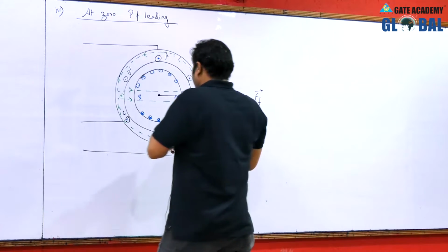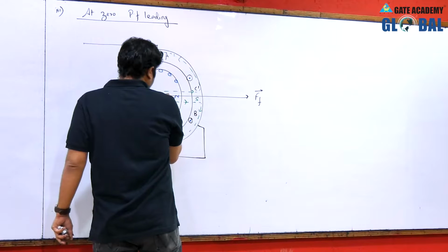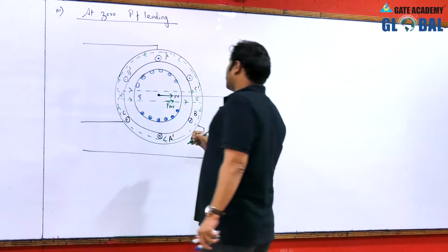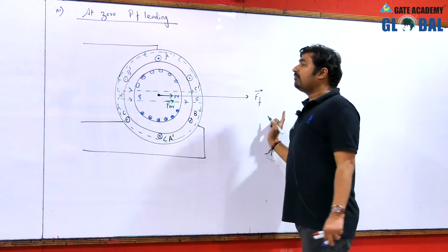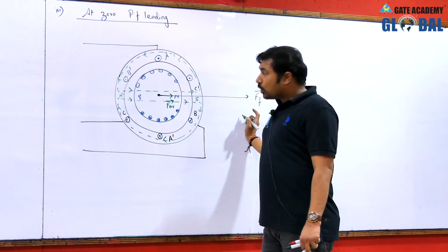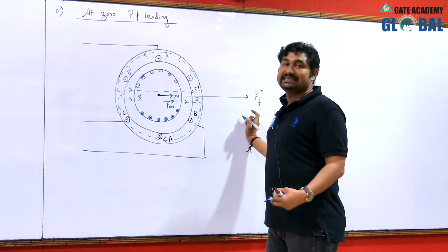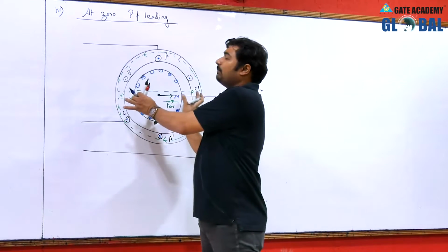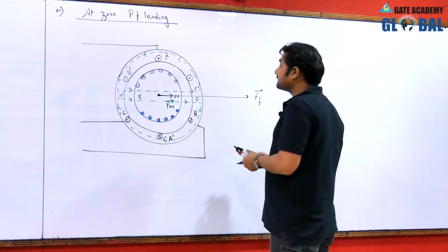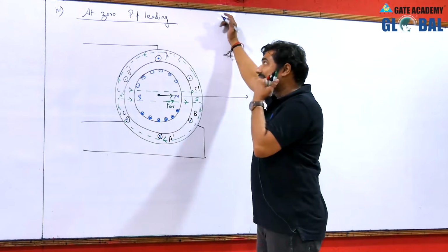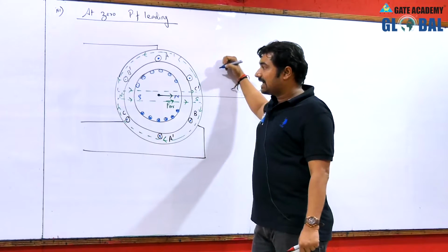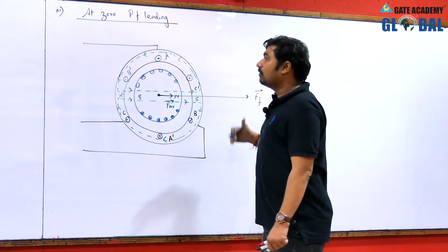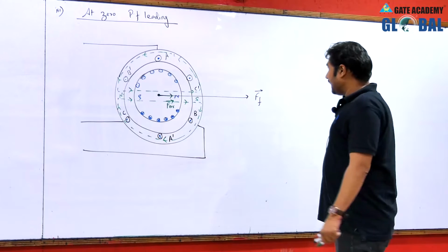Is it okay? Now, the stator field can be represented as armature MMF. So, you can observe the armature MMF and field MMF are both in the same direction. So, overall magnetization increases. Both the magnets are seen to be one big magnet. It means at 0 power factor leading, armature reaction has a directly magnetizing effect, and the overall flux will be more than the applied field flux.